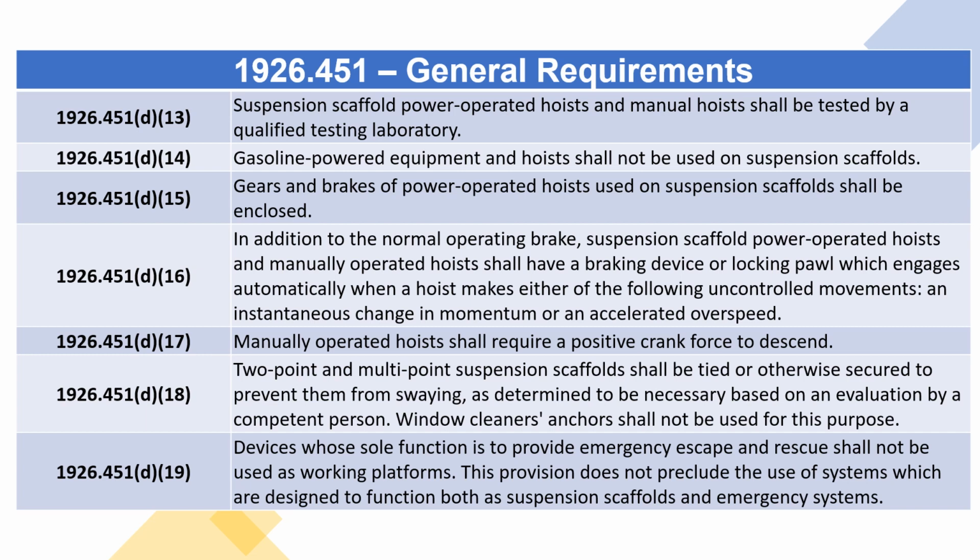1926.451(d)(13). Suspension scaffold power-operated hoists and manual hoists shall be tested by a qualified testing laboratory. 1926.451(d)(14). Gasoline-powered equipment and hoists shall not be used on suspension scaffolds. 1926.451(d)(15). Gears and brakes of power-operated hoists used on suspension scaffolds shall be enclosed.